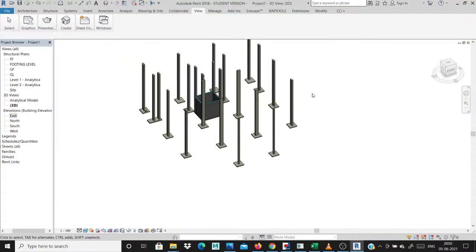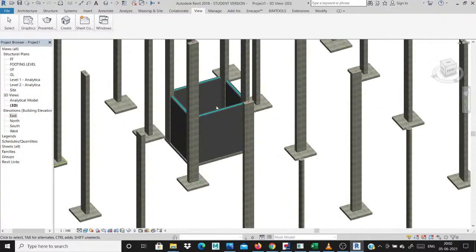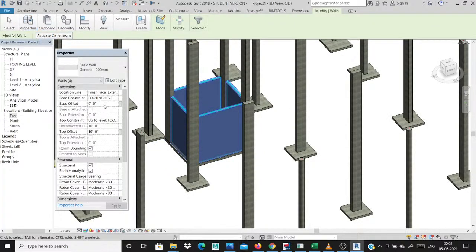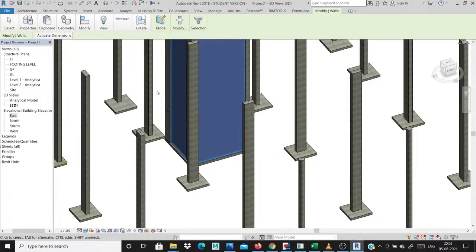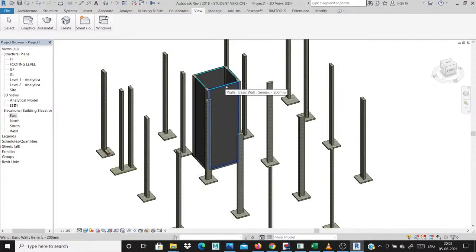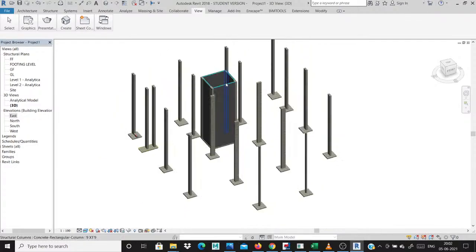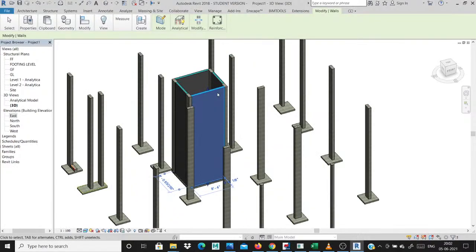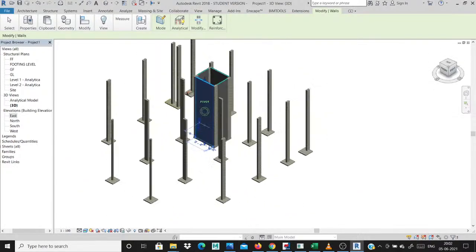The next one, you will create the shear walls on top also. Simply select all the shear walls, go to properties, then go to our basement height. Our top height is 30 feet. Simply click apply. See this, already the 10 feet is there and I need 20 feet height, total 30 feet height. See this, automatically it's created the staircase level also. This is our lobby, lift lobby.